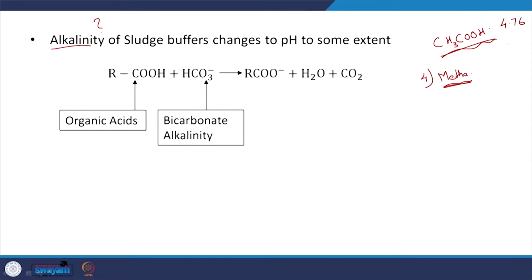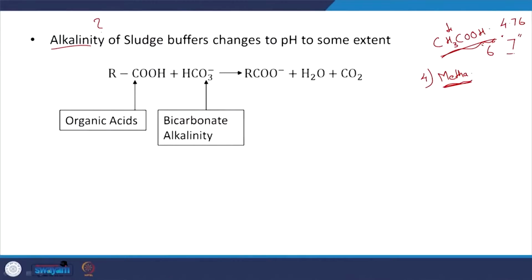So, it can bring down the pH, depending on the concentration, from the neutral pH to maybe 6 or so. And as we looked at in the previous session, we know that methanogens, which are the key to this process, are going to feel adverse effects when the pH is 6.5 or so, right. So, you want to control this anaerobic digester turning sour, right. We do not want this digester to turn sour, that is one aspect to keep in mind.